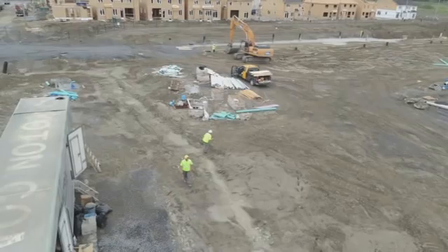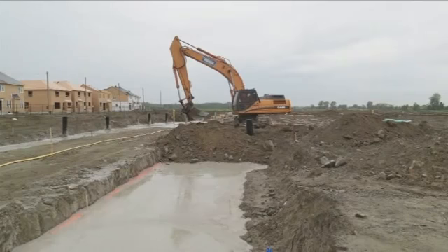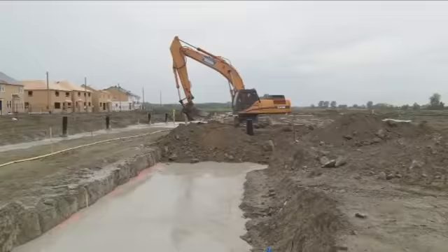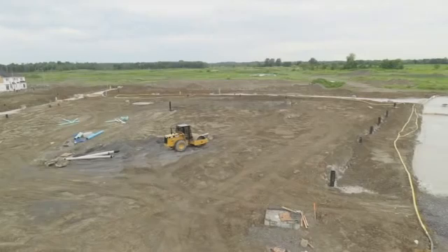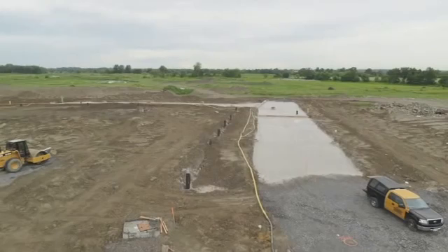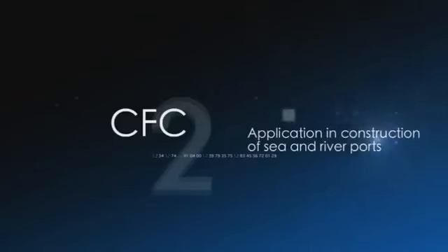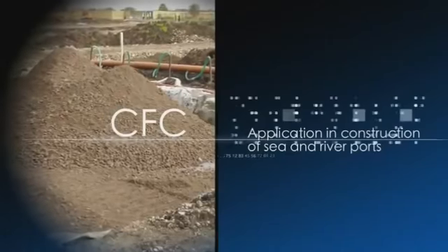Cellular concrete protects pipelines very effectively from external forces, impacts, dynamic influence, and so on, while at the same time it is a perfect thermoinsulator, which allows reducing the excavation depth with an obvious economic benefit. CFC is also easy to cut with any type of tool, including a hacksaw, and to pour in the places of repair, forming a monolith. Application in construction of sea and river ports.